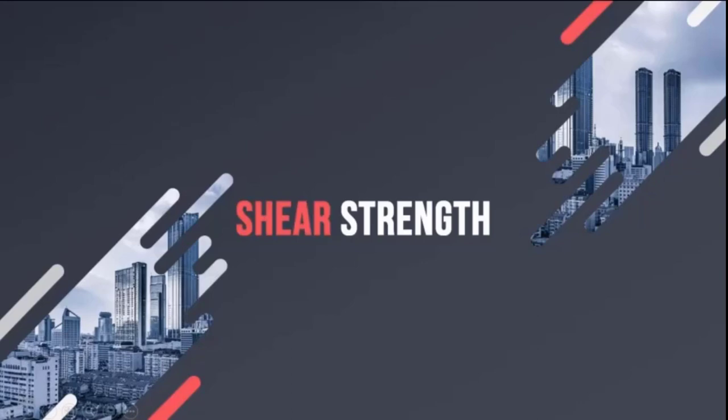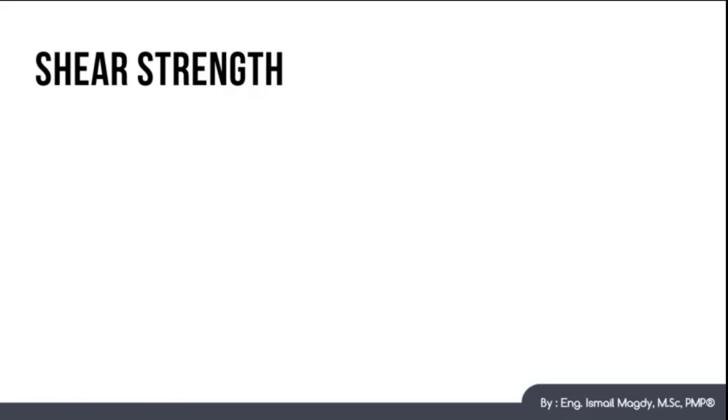In this video, we are going to talk about soil shear strength. Shear failure is one of the most common failure mechanisms for soil, and especially for slopes and embankments. If we have a slope like this one here, the most common failure mode of this slope is going to be by this portion of soil sliding in that direction. This line here is going to be called the surface of failure.